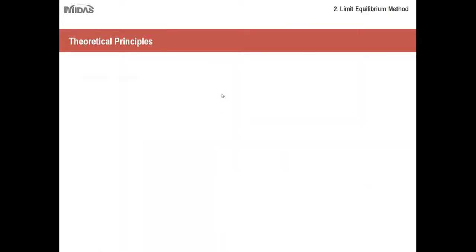Okay, so let's talk more about the theoretical principles, more specifically the method of slices. So the first thing to remember is that it's based solely on statics. That's something that a lot of engineers are surprised about when they first learn about the limit equilibrium method. Because what typically happens is they start using these programs without understanding the concept behind it. So when they realize that it's based purely on physics, it's a surprise to them because it's very simple and straightforward in that respect.